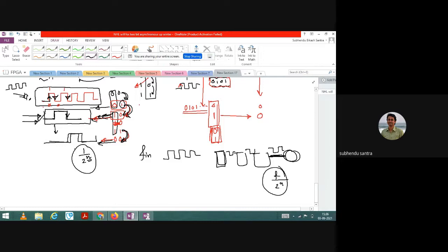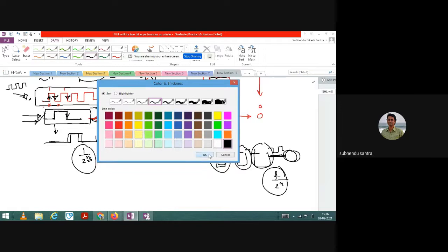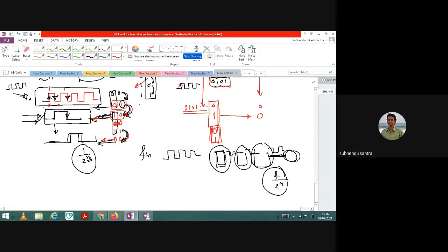Okay, so that's why this kind of programming or sequential way of programming is not good for the FPGA, okay, or VHDL code. But sometimes we cannot avoid it, sometimes we want. Okay, sometimes we want that the second process will only depend upon the execution of the first process. So in that case, definitely you need to use the sequential way of writing the VHDL code. Okay, so I hope you understand this process of writing the up counter using asynchronous manner. Is it clear to you?